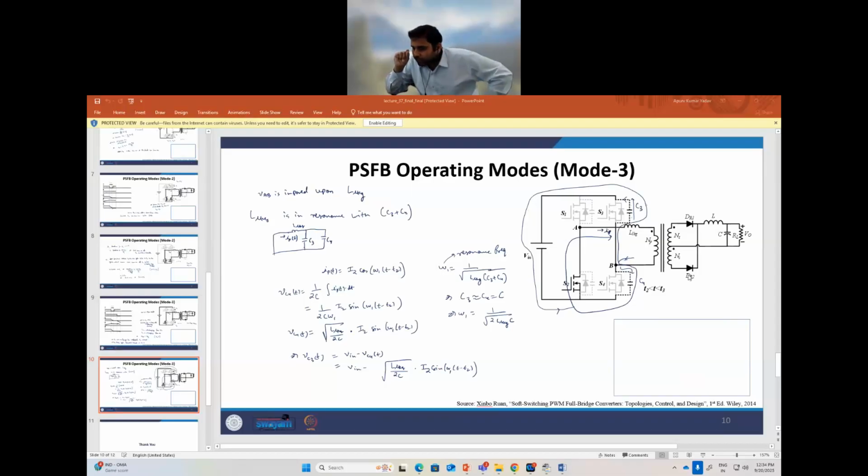When you go to light load condition, you can definitely have the problems that your power factor is not matching, your power factor is not going towards 1, and your THD is very much off. But near the full load condition, THD wise, I don't think there will be a problem. You may not have taken the inductor value properly, or the ripple in the inductor current. Have you taken all those things correctly? Yeah, I will check once. I will recalculate the inductor and the capacitor. The DC link capacitor value is okay, but the inductor is important.